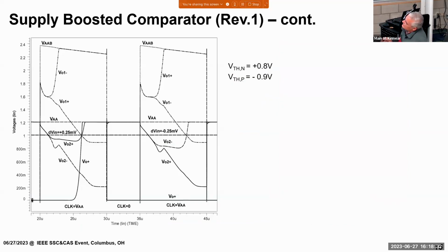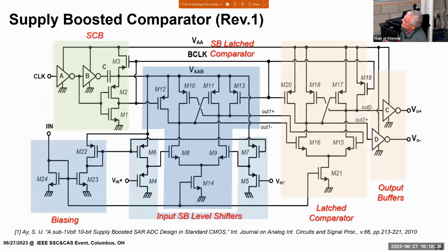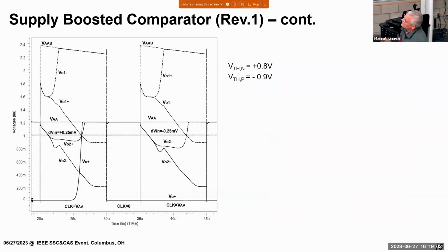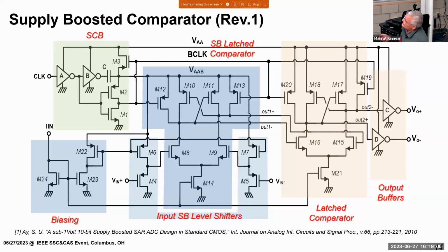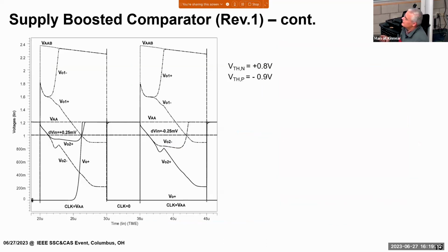But again, you mean this drops, but this doesn't drop? So from the schematic, why does the supply drop, but the output doesn't drop? No, the supply drops, right? Because you're saying that once it's boosted, during the decision-making it's draining the capacitor. But your output still is the same, even if your supply is varying, because you have a positive feedback there that locks this up in one direction. And that direction is very difficult to turn around, even though the supply is dropping.